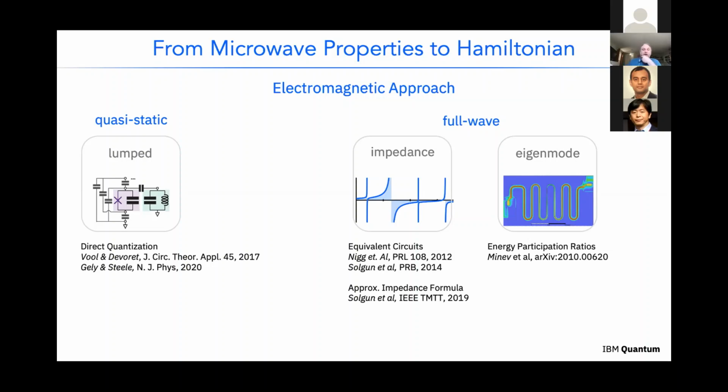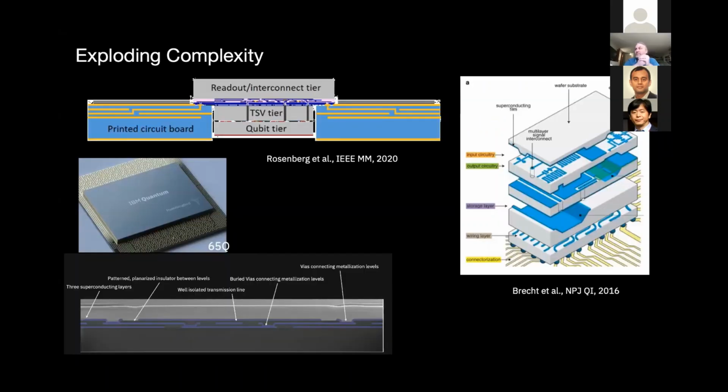So why am I a little bit scared of designing these? Well, if we want to build logical qubits, we're not building devices with 20 or 100 or 1,000 qubits. We're designing devices with millions of qubits. And what that means is that the simple two-layer approach that I showed you before breaks down just because there are too many signals involved. In most of these technologies, you have basically one I/O line per qubit. And so if you look at the types of devices people are planning for the next few years, you're beginning to see these complicated flip chip designs, integrated multi-level wiring, integrated 3DI, 3.5DI, 2DI.